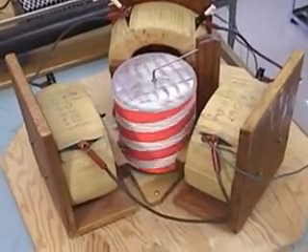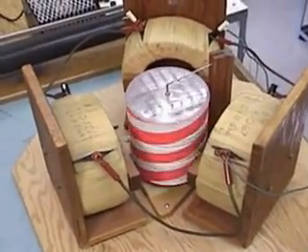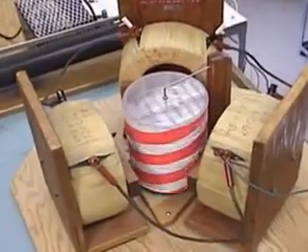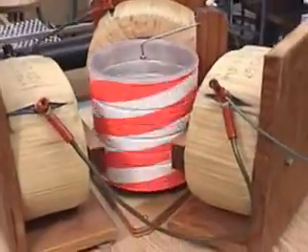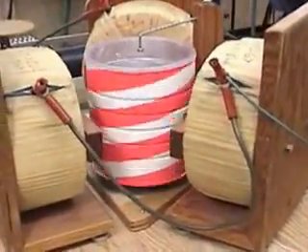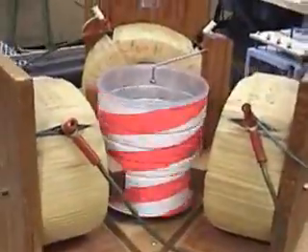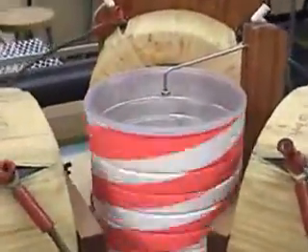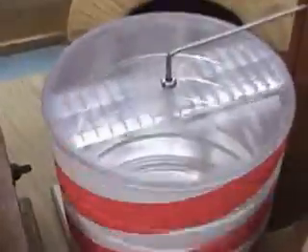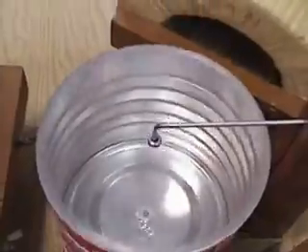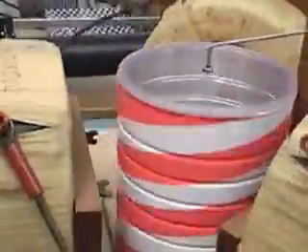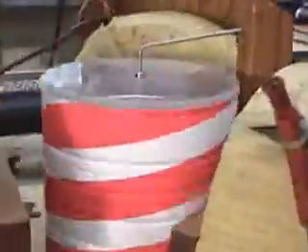The currents produce a rotating magnetic field. The field induces currents in the can and applies forces on those currents. The coffee can rotates. Let's make sure there is nothing else making the coffee can rotate. If we have a peek inside the can, we ascertain there is no hidden mouse happily running around and making the coffee can rotate. There is nothing inside, and there is no hidden tiny electric motor at the bottom either. There is only a spindle, a passive spindle.